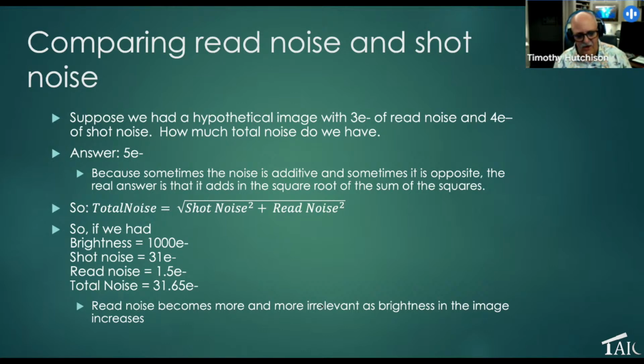My opinion, heck no. As the image becomes brighter and brighter, the contribution of read noise becomes less and less significant. It doesn't matter what our gain is. It doesn't matter where we're choosing to shoot, because that little tiny contribution of read noise is going to be insignificant when we compare it to what we're getting from shot noise. So in my opinion, the read noise becomes more and more of a non-issue. Just get brighter and brighter and brighter. I can already hear you guys disagreeing with me, but trust me, this is true.